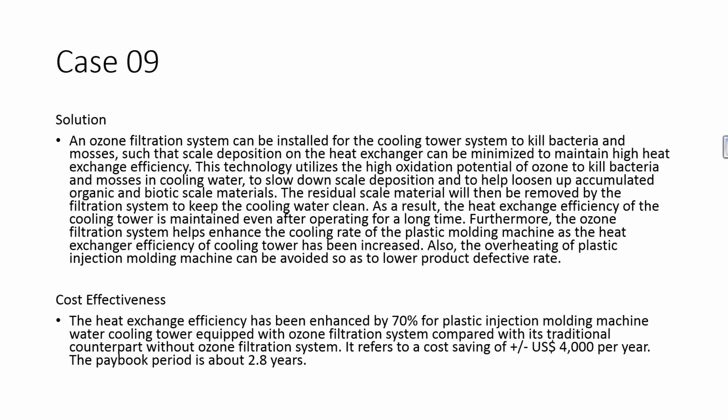This technology utilizes the high oxidation potential of ozone to kill bacteria and mosses in the cooling water, to slow down the scale deposition and to help loosen up accumulated organic and biotic scale material. This residual scale material will then be removed by the filtration system to keep the cooling water clean.